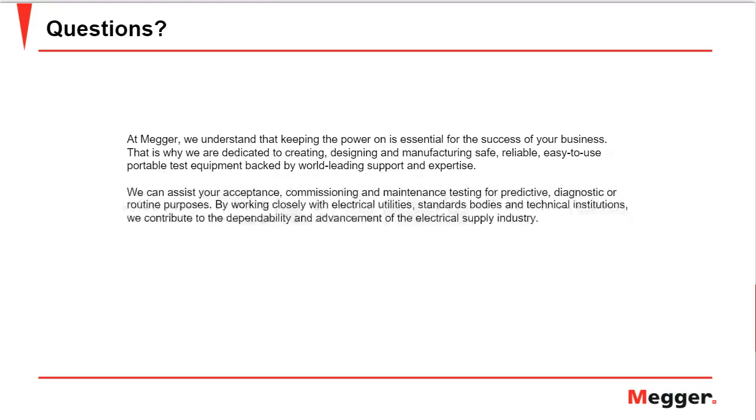If the transformer damage curve is not available from the manufacturer, what I would do is, it depends how old the transformer is, but there is information in the IEEE standards. There are guides that deal with how to construct the damage curves for different types of transformers, whether they are oil-filled or dry-type transformers, and they classify the transformers in different classes, class 1, 2, 3, 4, depending on the type of transformer.